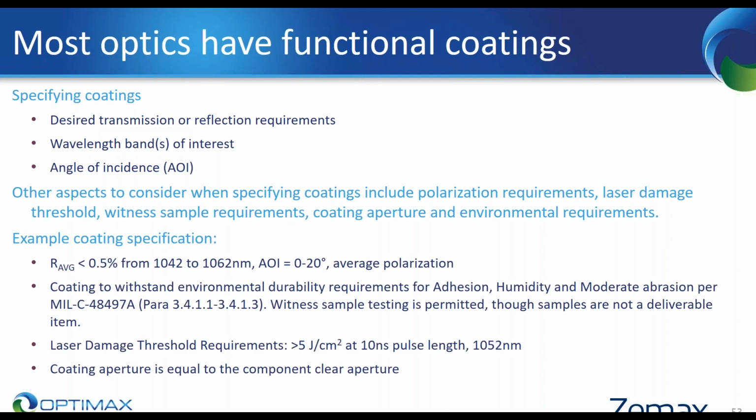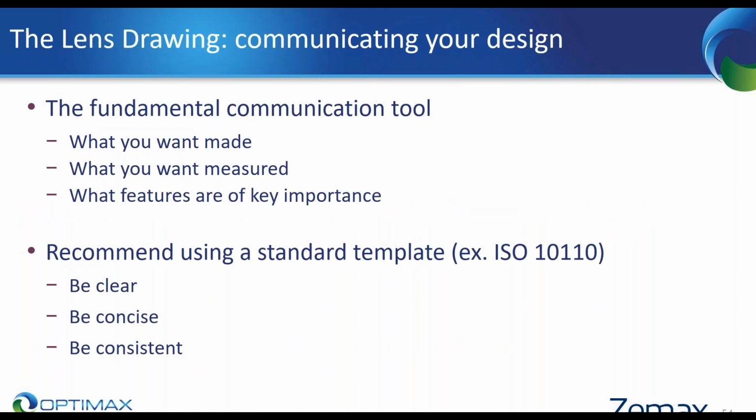And I'm going to now move into my most confusing slide that I have for the entire day. But why I want to highlight this is because of all of the information that we walked through and talked about today. On the right-hand side is the tolerancing chart, on the left-hand side is an example drawing. This is adapted from a really great reference paper and poster. I have the reference below, where they walked through translating the American MIL drawings to ISO 10110.